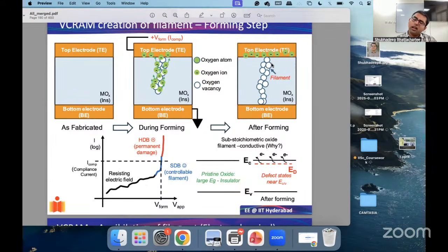Why will there be very little current in the device? Because this is an insulator. But as we know, even an insulator has a finite bond strength or finite dielectric strength. Once it reaches a particular critical electric field, what will happen? The bonds will start dissociating. Of course, the bond energies are very high. For SiO2 it is 9 eV or whatever it is, but there is still a finite limit to it. It's not infinite. So once you start applying a small electric field, just imagine these are the molecules in your dielectric.